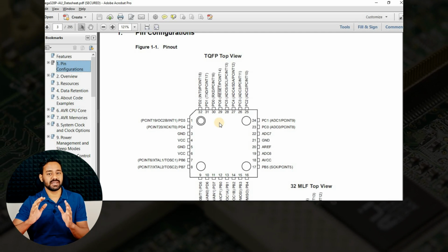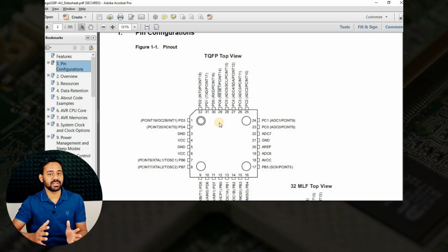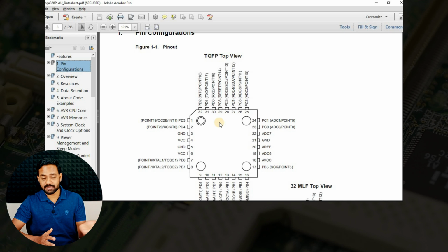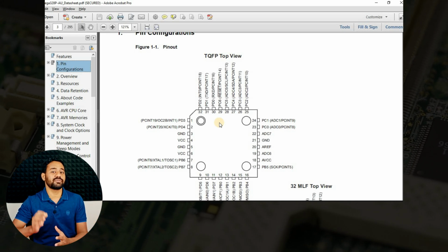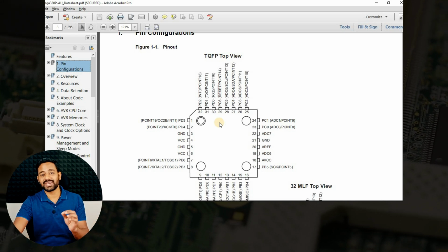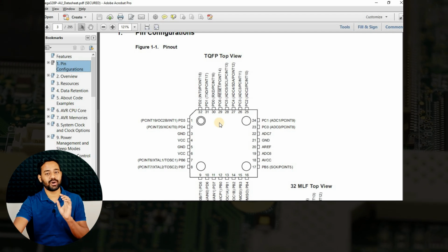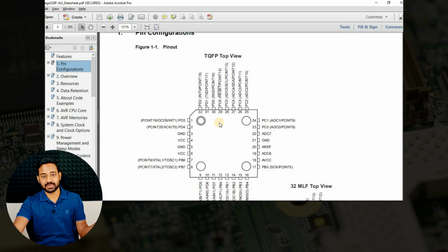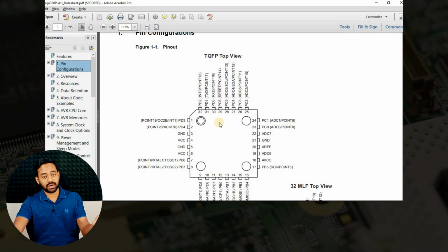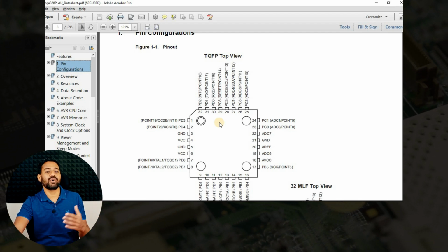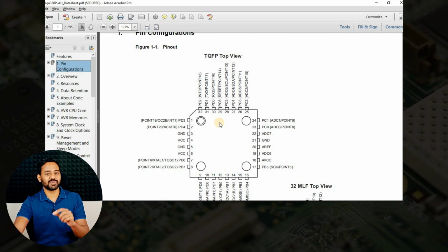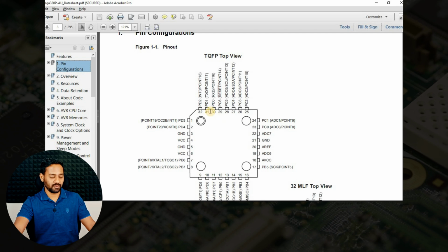Atmega328P-PU, which is a through-hole version of this microcontroller, and it consists of 28 pins. Whereas this particular microcontroller consists of 32 pins, and all the pins are not directly swappable or directly mappable. That's why you cannot use that particular schematic symbol of the through-hole version for this footprint. So make sure that you create the schematic symbol once again.